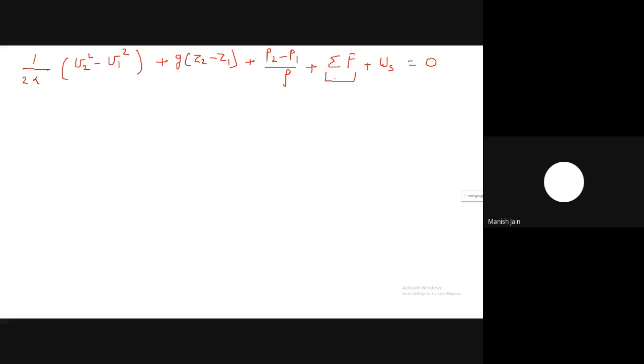It is the laminar region or the turbulent region. Based on that, you can define the value of alpha also. The other parameters you can calculate from that parameter only. So the water properties: the density of water at 20 degrees Celsius, you can take from the data book or the appendix, that is 998.2 kg per meter cube.